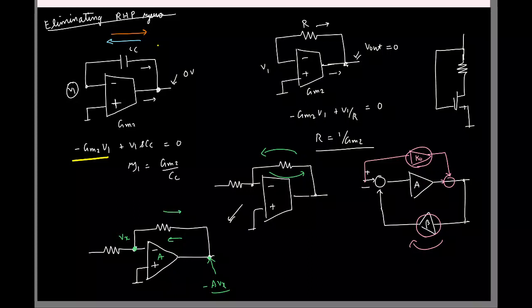Okay, but when you have a VCCS like this, that is only providing a constant current. Okay, so if along with this current, if you have some other current flowing from the resistor, both the currents will add up, flow into the effective resistance at the output and generate the output. Okay, so that is why this feed forward is a problem here.